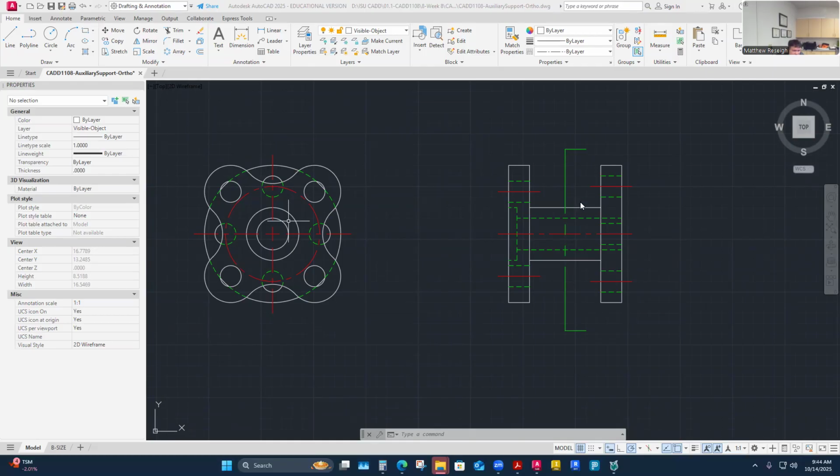It's really not to expose this, although it will expose the outer diameter and the inner diameter of this through bore here. It's dimensionable, but it'll almost look like it does right here anyway. Maybe it'll be a little clearer that this is the counterbore with its detail work, and I will have another place to apply a dimension, the inner bore diameter.